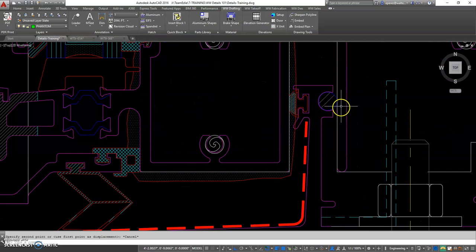We have this aluminum rod, which only occurs at the verticals. This helps with installation, as well as putting some pressure up against this gasket in the front, which is where we don't want water to be able to come up through. So it helps create the pressure equalization, as well as helps us defend this water line.